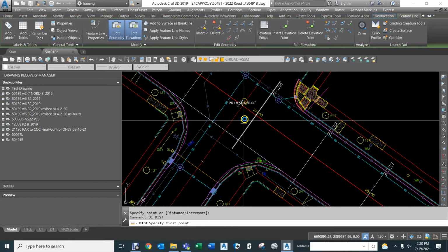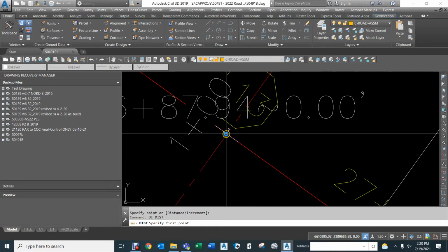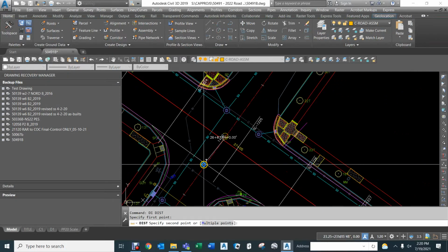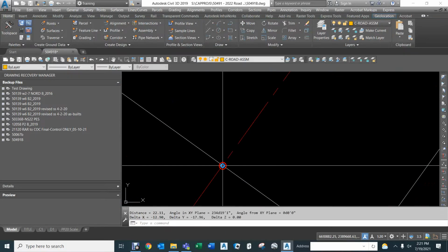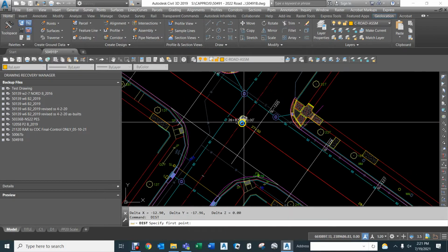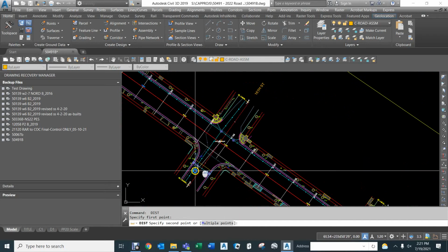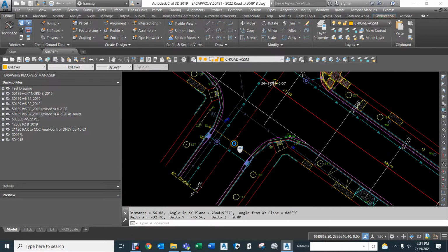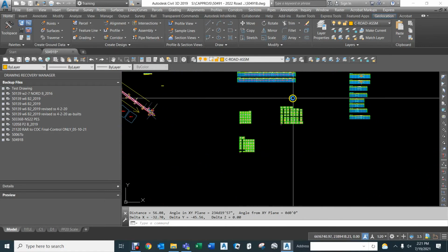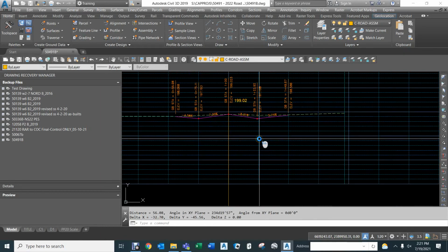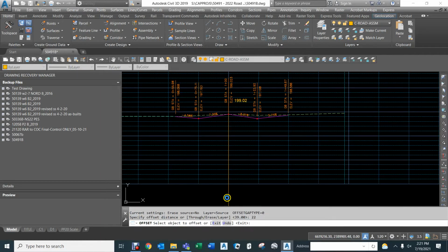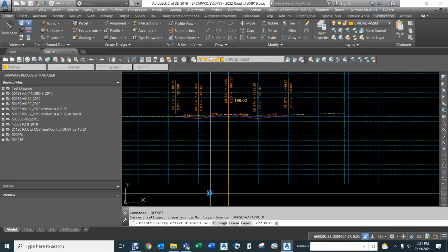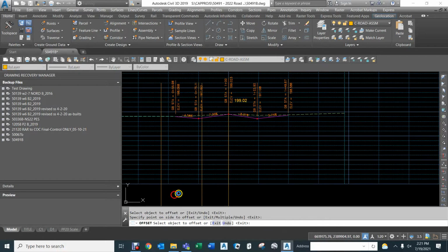Now the distance, we'll take a quick distance, just close, doesn't need to be exact. Here to here is probably 22. Yep, we're going to just call it an even 22, and we're going to call this point back here, just approximate, even station, 56. 22 and 56 is what we need to be. So we go back to our profile here. We say offset 22 to the left and 56 from the center line out. Those are our two tie-in points.